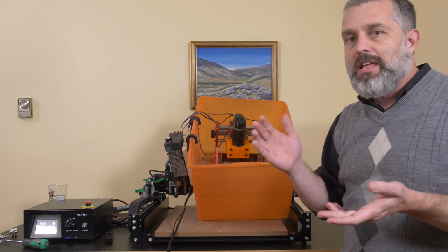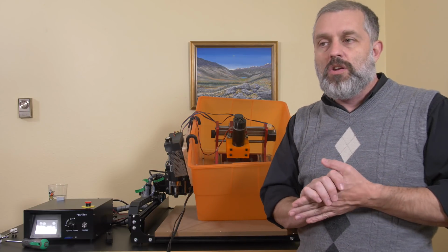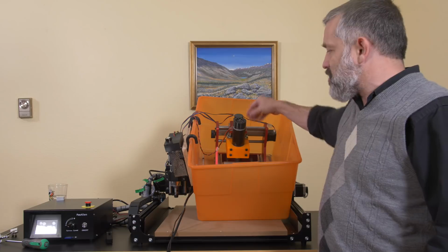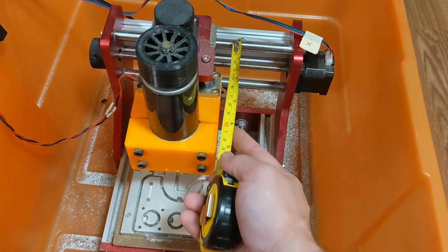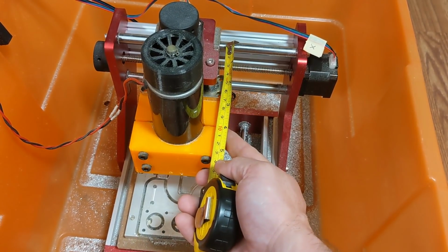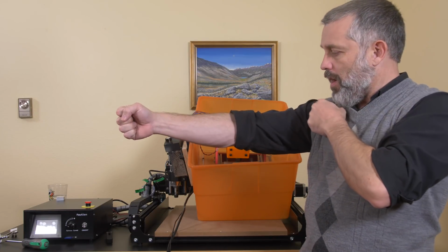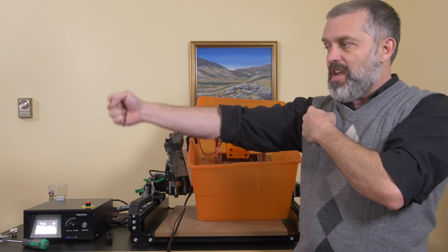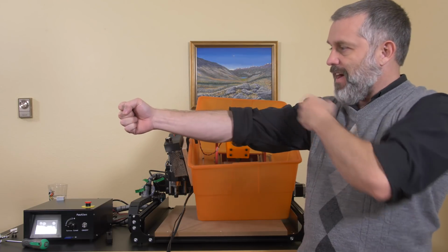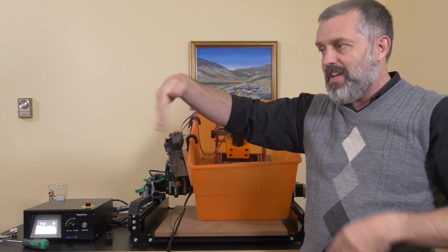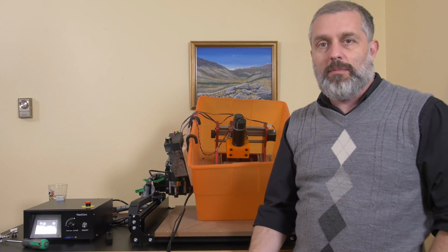Now, I didn't measure it. Maybe it's only a 1/1000th of an inch wiggle, but this is cantilevered a good 4 inches out there. So we have some seriously cantilevered forces. A 1/1000th of an inch here could equate to 5/1000ths of an inch out there, and 5/1000ths of an inch is significant when it comes to chatter.